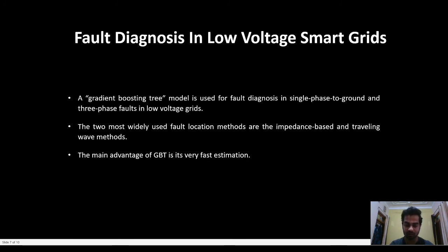They rely on detection of the wavehead, which can sometimes be quite challenging. They depend on the line parameters, which vary a lot on distribution systems since the speed of the wave is based on the inductance and the capacitance of the lines. They are also vulnerable to external signal interference.